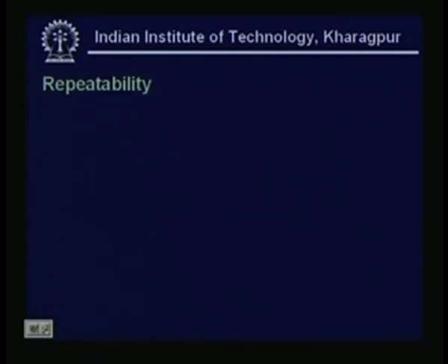Now, repeatability is very important in instrumentation. If there are thousands of instruments in a big plant, thousands of sensors for temperature, pressure, flow, you cannot expect that you will calibrate the instruments every day or once in 7 days. Usually the typical norm is routine maintenance, routine checking of all this calibration, but if there is a fall in the quality of some product, then we will talk about the instrument calibrations or sensor calibrations, otherwise not.